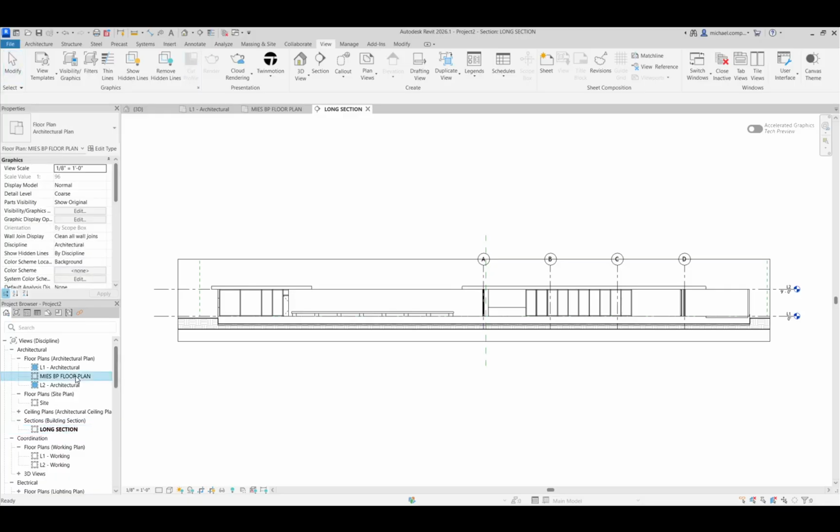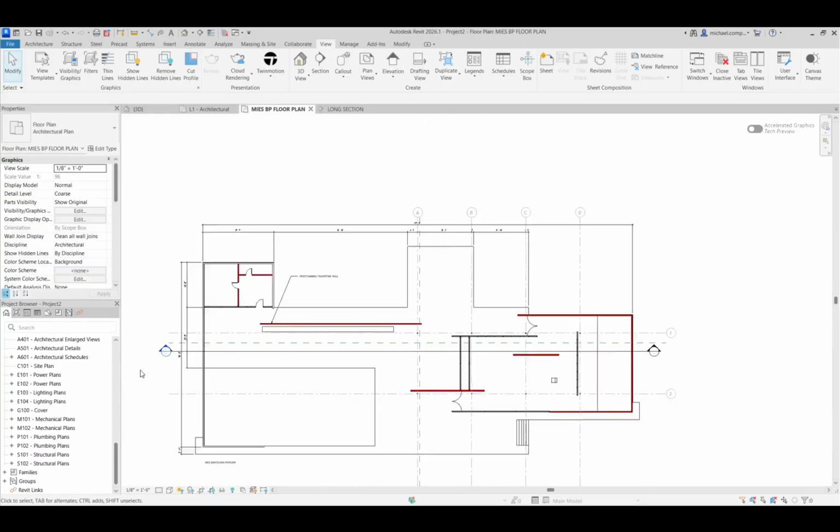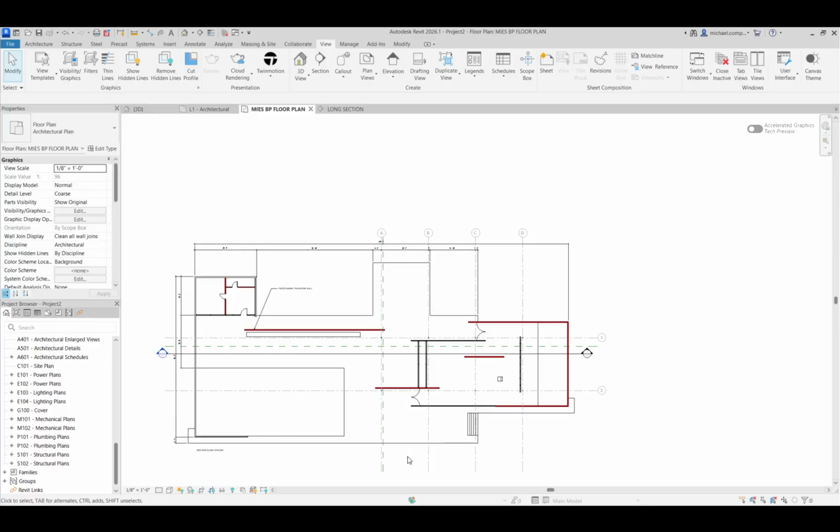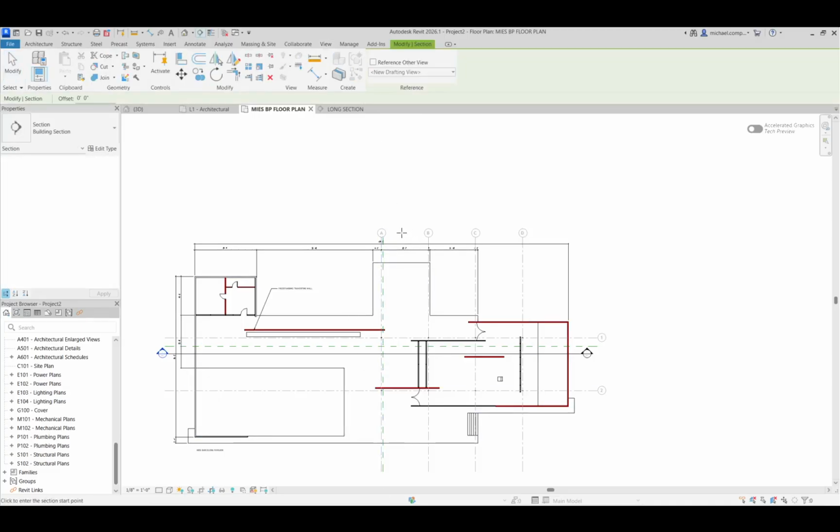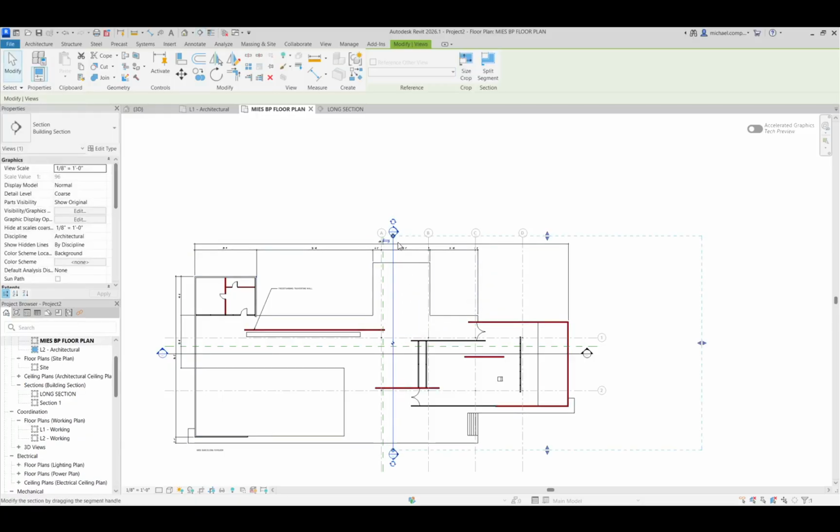And then I'm going to go back to my floor plan, and I'm going to cut the next section this way. I'm going to go right through the center of this pad. So section marker, drag down, and then you see what it did again. It's looking to the right. It's cutting and looking to the right. And that's the section I want.